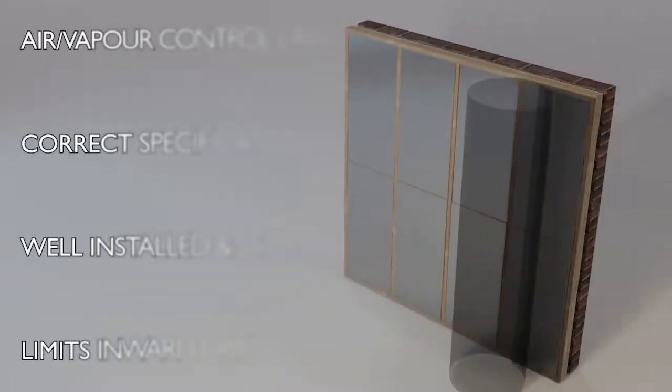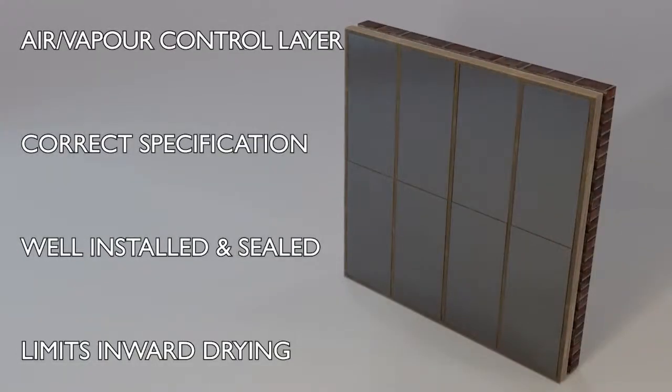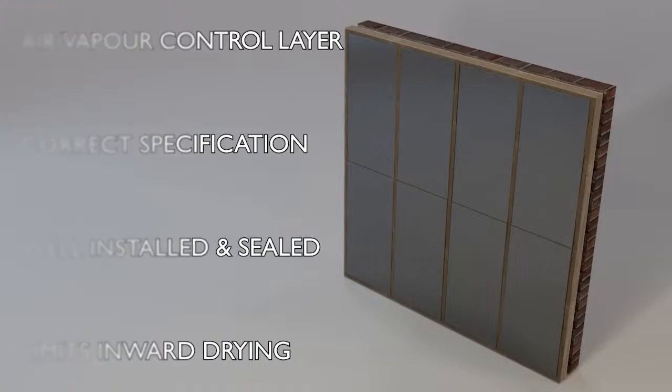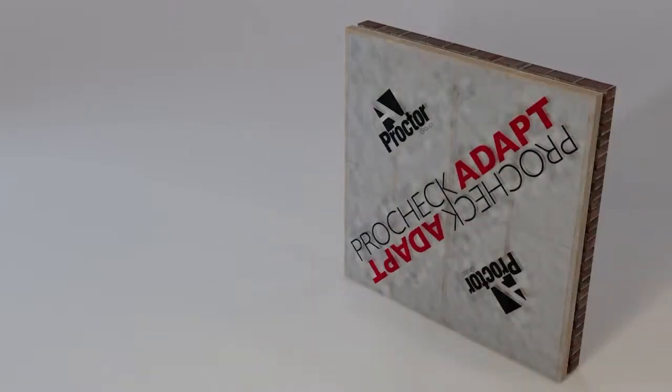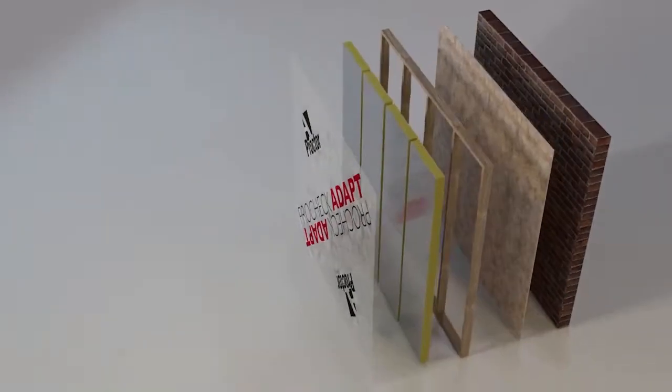A possible solution to this is to use an air and vapor control layer internally, but again this must be correctly specified and installed to be fully effective. If the existing wall relied on a degree of inward drying out, then adding an impermeable layer may lead to issues. In this situation, variable resistance vapor control layer membranes such as our Project Adapt can provide a solution. This type of membrane varies its vapor resistance in response to environmental conditions, becoming more resistant to vapor in winter and more permeable in summer.